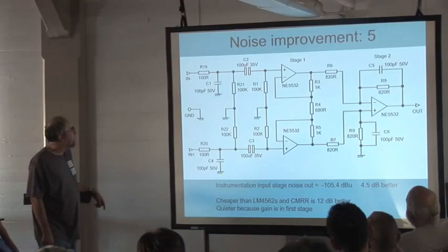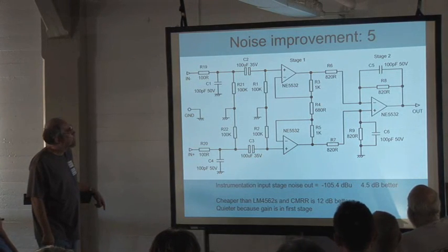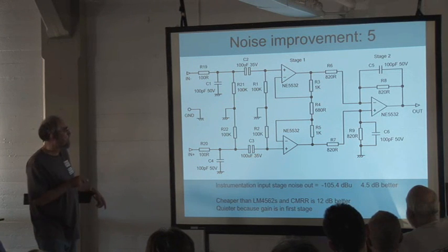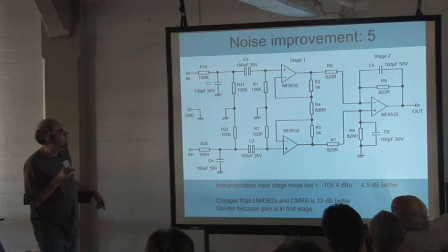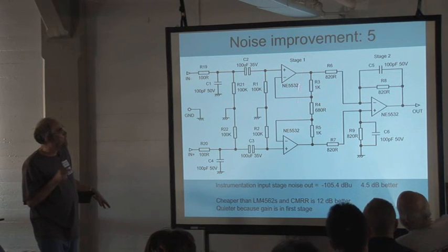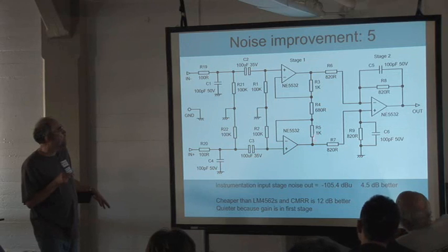Right. Now this is an interesting one. Since I wrote the book, I've been playing around with instrumentation amplifiers, and this is this configuration here, where you have a shared resistor and sort of gain there. And as you probably know, the great thing about this is that common mode gain is always 1. It doesn't matter how much voltage gain you've got, which is set by this, the common mode gain is always 1, and that doesn't depend on resistor matching at all.